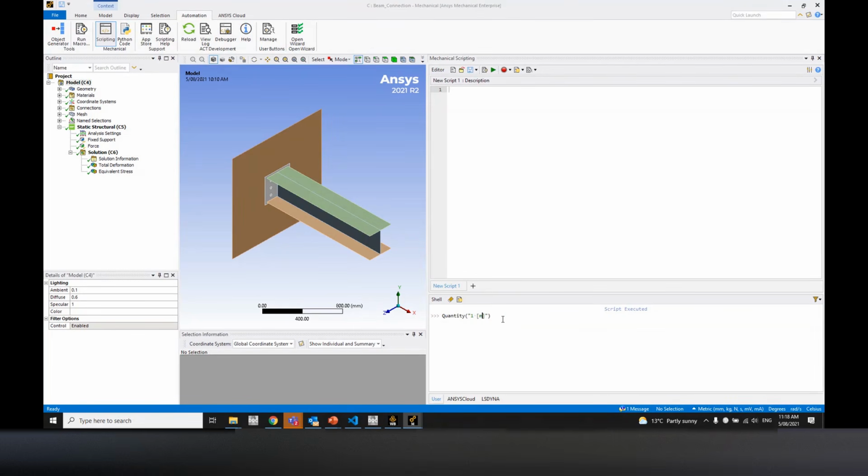If you want meters, you can write meters, and in the solver it'll keep it consistent in the backend, so you don't need to worry about units for now. But the other way I found of defining is you can just write 1 comma and then the unit in quotations, so that's another way of defining units. There are a few ways, so it's really up to you how you want to define a particular number and variable, whether it be acceleration, pressure, length, force, etc.